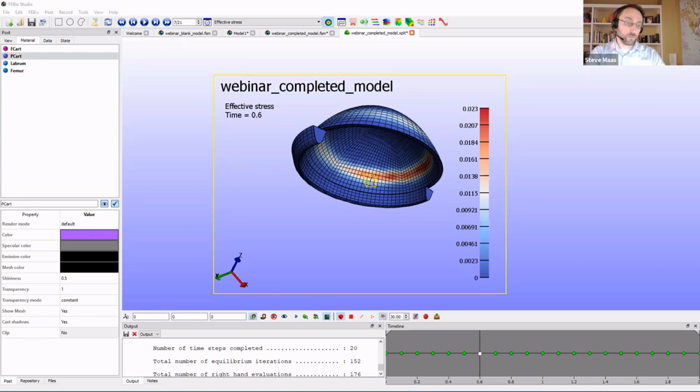Is it possible to include both the contact boundary and, when the surfaces are not in contact, a depth-dependent pressure? So the pressure is a boundary condition that you can prescribe via a mathematical equation. So you can, in that sense, prescribe a pressure that depends on the position or the depth. I'm not sure if that's what you're referring to, but I guess yes. If that's what you mean, then yeah, you can prescribe the pressure as a function of the position, and in that case, get a depth-dependent pressure.